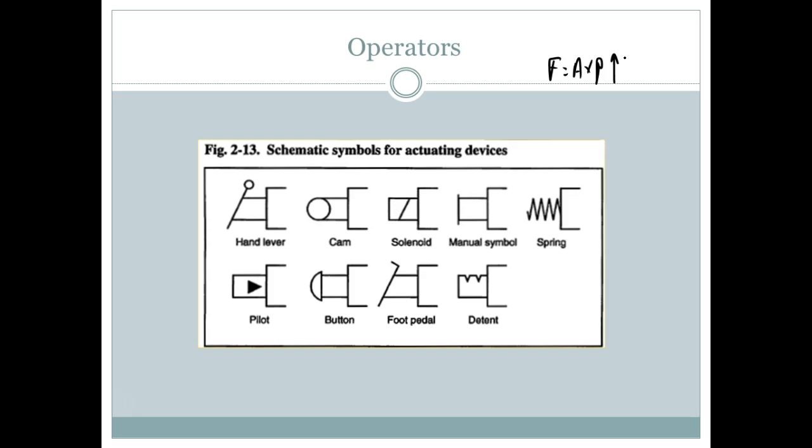So what we have, though, guys, is a pressure source available. So what we do is we'll have a solenoid that opens up a little valve. And I'm going to show you a video. Then this lets the air pressure come through, and then the air pressure or the hydraulic pressure shifts the spool. Right? You understand? So, you know, our system we're running, I think, at 60 psi.